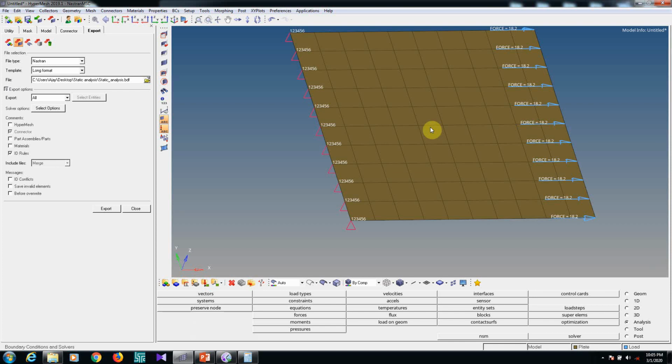If it is a planar area, simple coarse mesh is enough, and you will get the right result. If it is a complex feature, wherever the complex feature is there you need to do fine mesh and the remaining area coarse. This will give approximately good results.